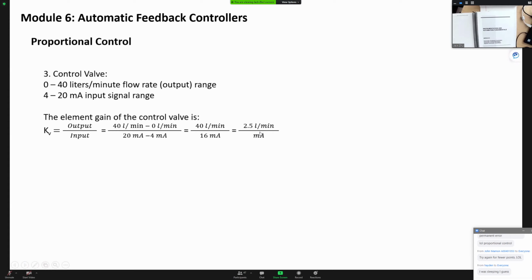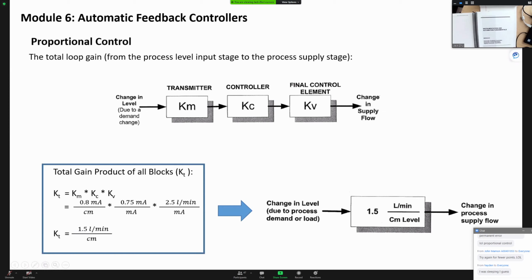If you try to change it to increase the flow or decrease the flow, that's where the controller sends out to the final control element. They're going to send out a milliamp signal to do the adjustment down there. But those calculations you don't need to worry too much about. It's a mathematical function.